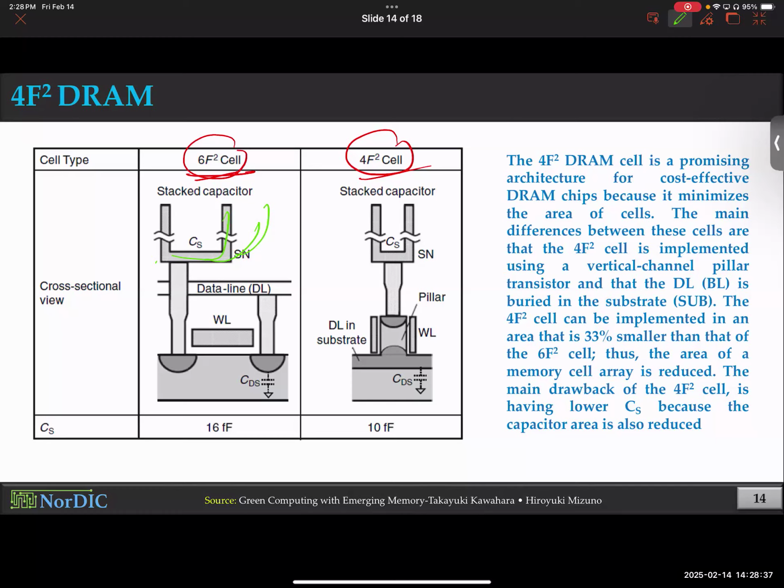And why am I putting so much emphasis on it? It's not just because of DRAM, honestly. These few lectures are so critical because they will create the foundation of the upcoming emerging memories. And hopefully this will be a given. The moment you see that you can put a magnetic tunnel junction on top of a transistor within its footprint, when I say within its footprint, you immediately think what? 4F square. Making sense? So engineers eventually managed to create the capacitor within the transistor footprint.